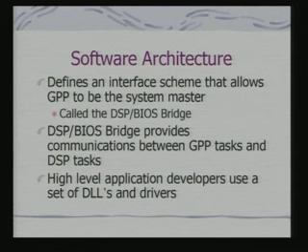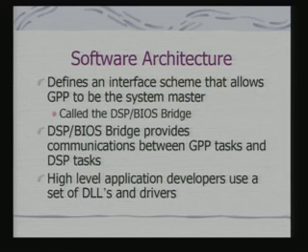And this can be used in a way that you are just using a uniprocessor system. So, the basic objective of using this DSP BIOS is that externally, for an application programmer, it would appear that he is just programming a single CPU, and internally the DSP BIOS is taking care of mapping subtasks to the DSP. So, high level application developers use a set of dynamic link load libraries and drivers and have the feel that they are using a single processor.